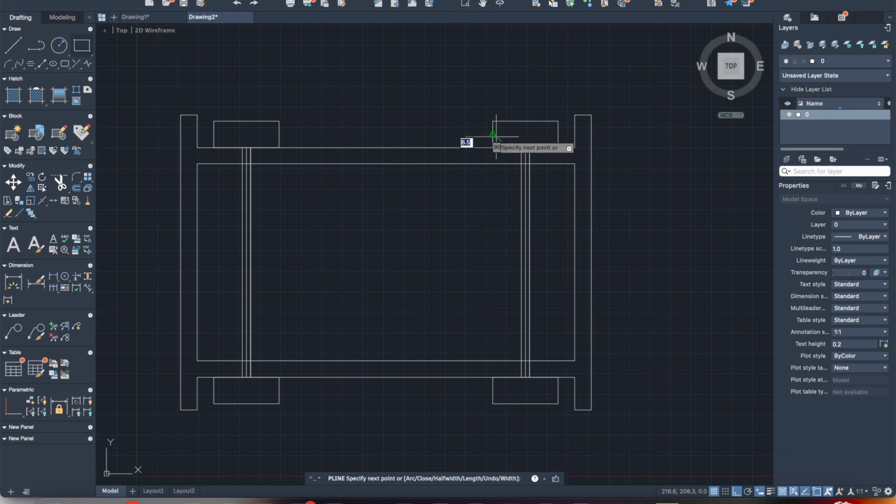16. You can see how important it is to have ortho mode on, because you're working so quickly, it's easy to make a crooked line. So definitely make sure that is on. Now we can trim out these excess lines. And remember, there's extra ones as well to clear out in my case, not yours, maybe.